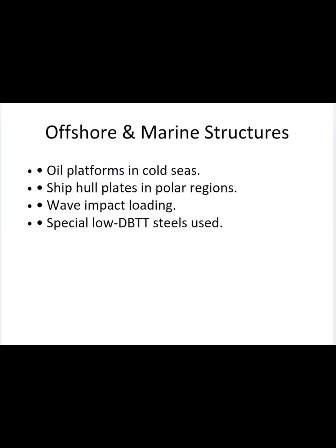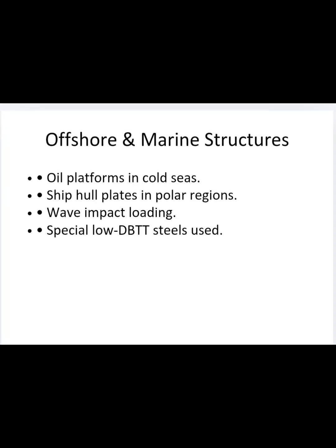Offshore and marine structures. These structures are subjected to wave impact loading and fluctuating stresses. If the material becomes brittle at low temperature, cracks propagate rapidly. So in this case also, low DBTT steels are used.